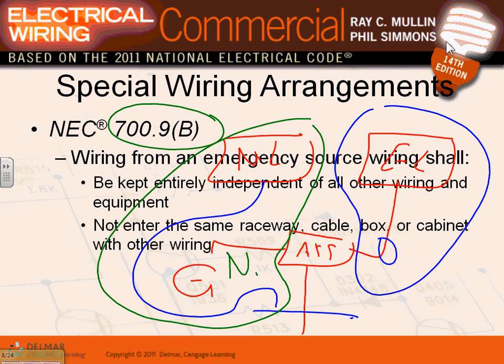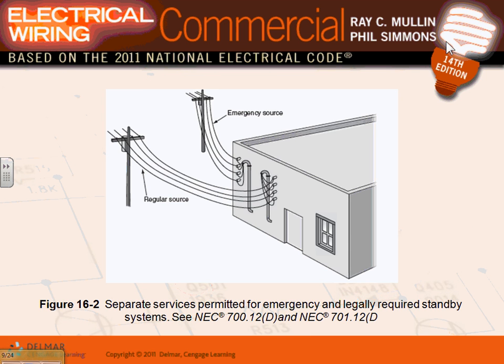Do you have your emergency lighting fixture and location? Do you have a separate conduit as well? If you have an emergency lamp in that light, you have to use a separate conduit for that. Yes, so you will have two branch circuits coming to that fixture. Two branch circuits. There's a nice example there. Okay, so a legally required standby system needs a separate service permit from the emergency system.